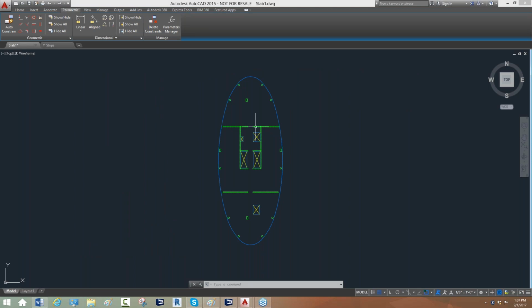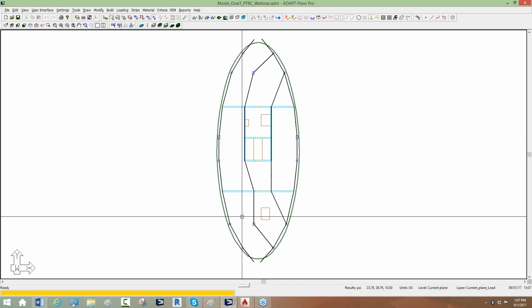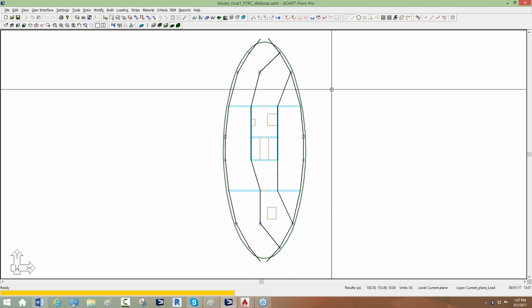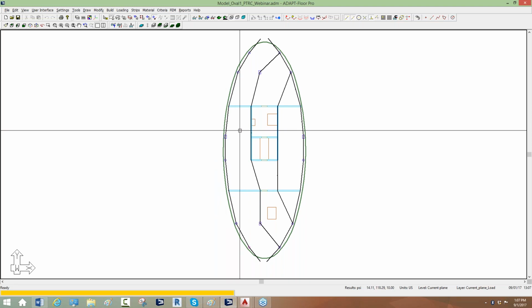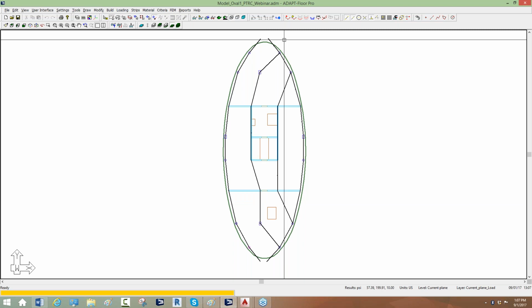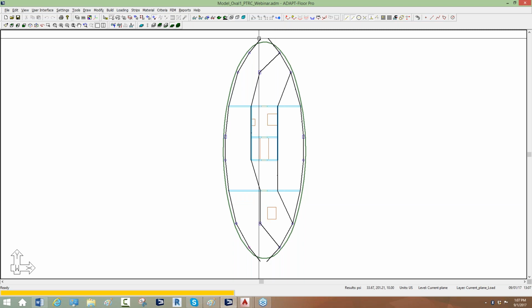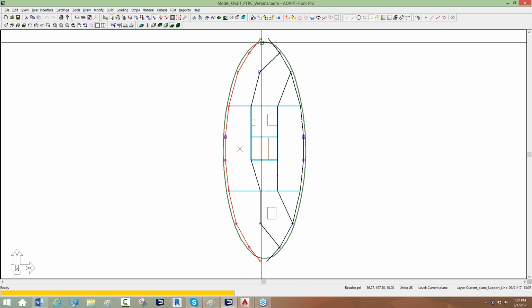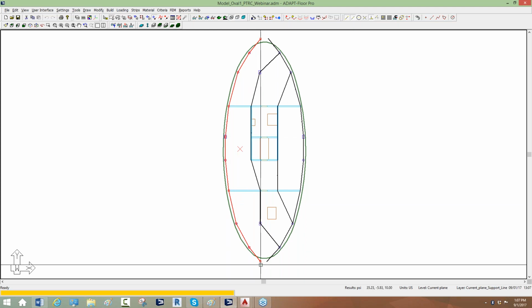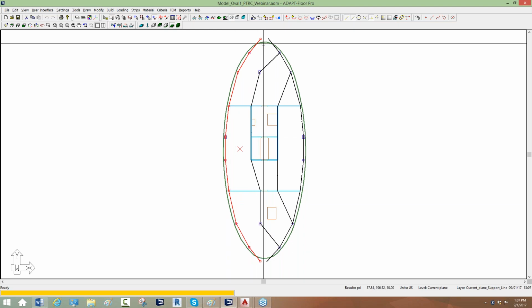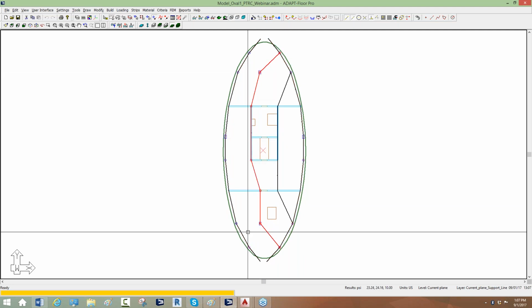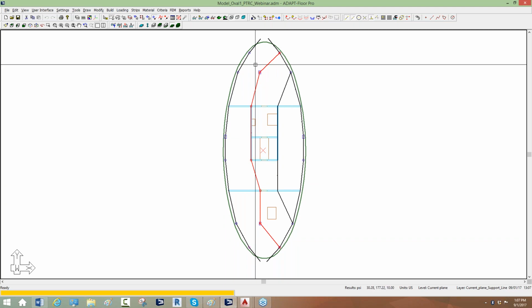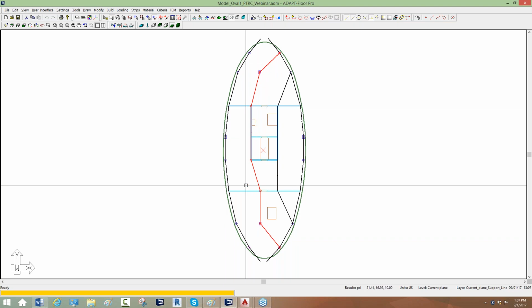So for our model here, before we come back to that, I want to show you what we've done in ADAPT Builder. This is our finite element program that I'm looking at. In ADAPT Builder, we have to go in and make decisions as to what the support lines are in this program. For example, in the y direction, I have a support line that wraps around the perimeter of the slab on both sides. And then I have support lines that go from column to column to column. So I've dictated the load path for the y direction in this model.